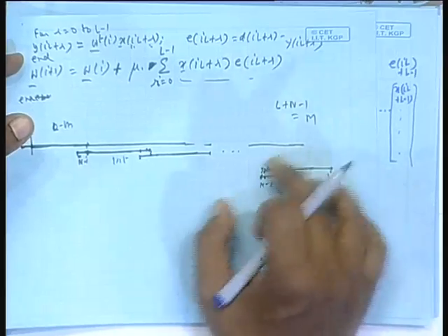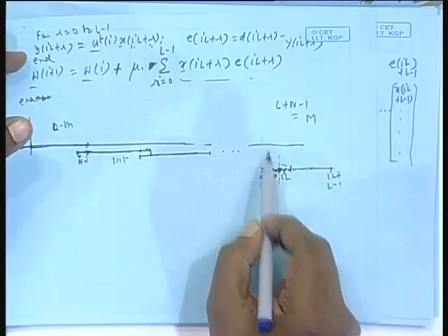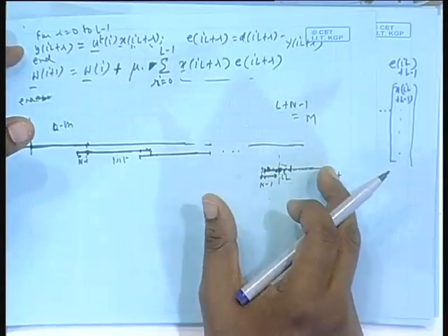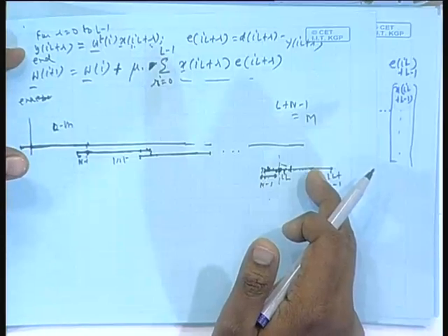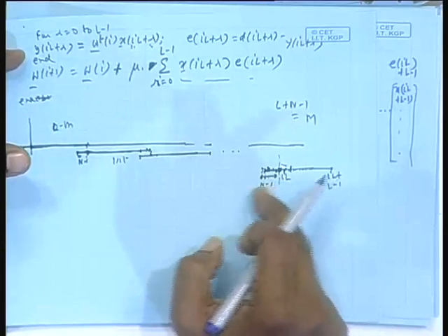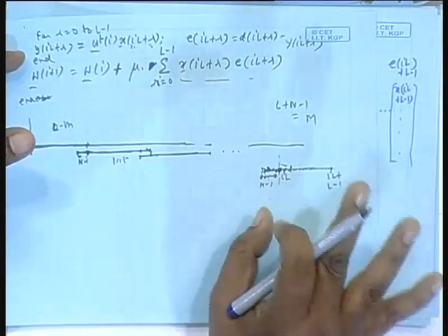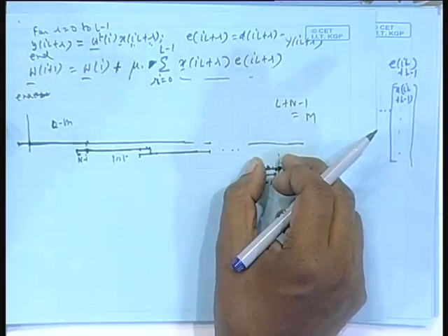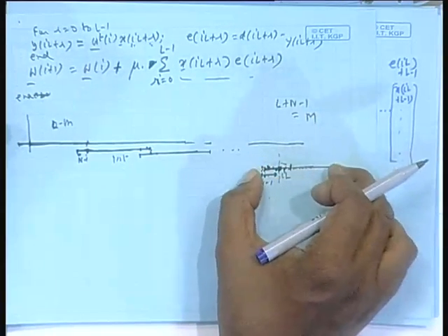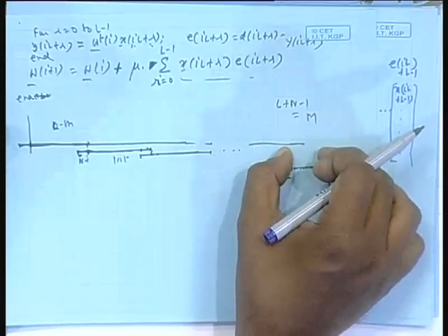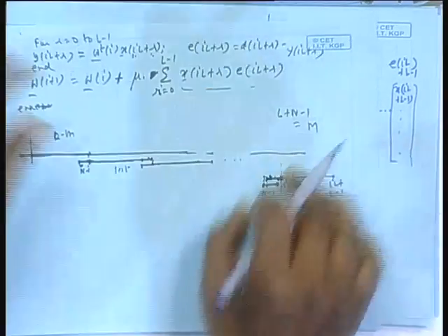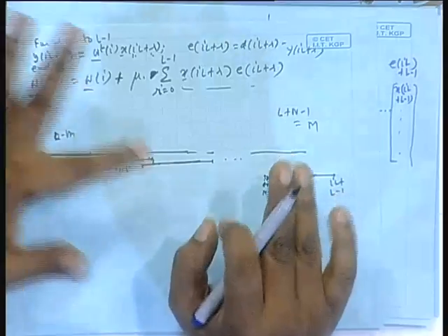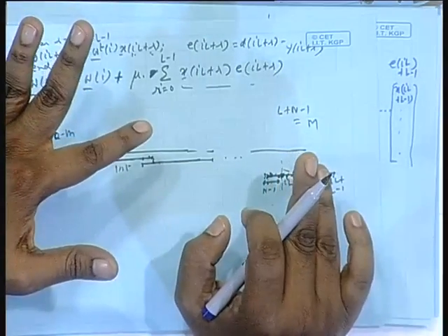This I need, because I am doing the overlap save method of filtering. So, the circular convolution thing was there, and throw away the first N minus 1 sample output and all that. Add zeros. This filter vector is length N, and this is L M. So, add those difference of zeros and then circular convolution. That we did yesterday, now overlap and save method.